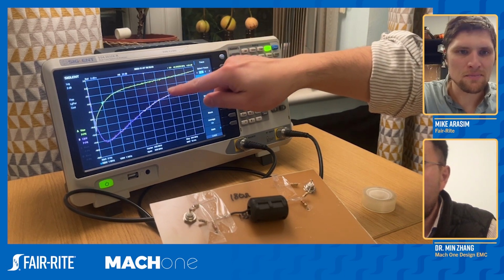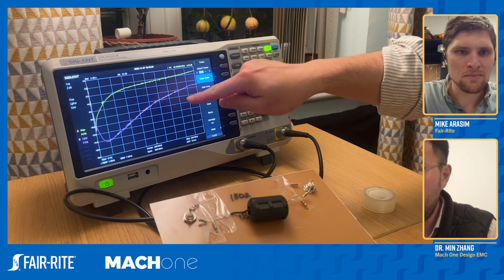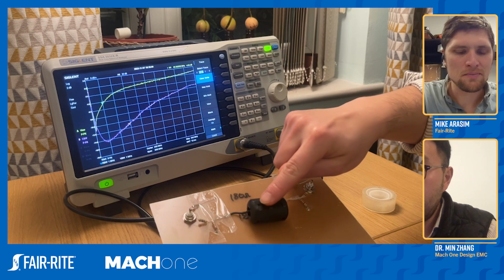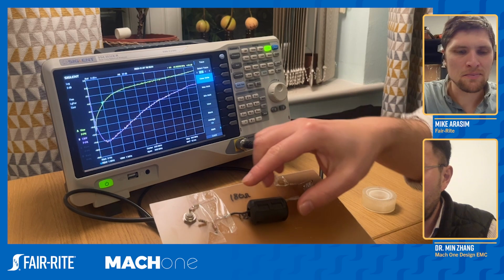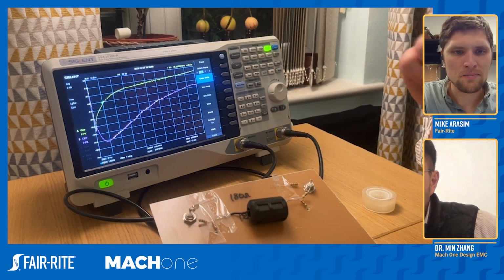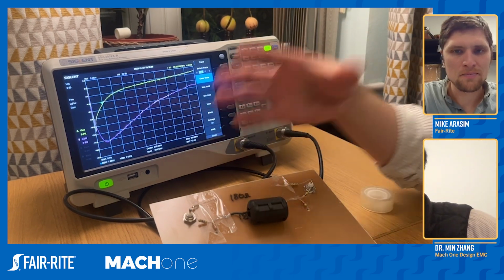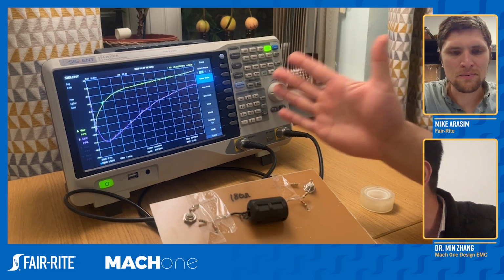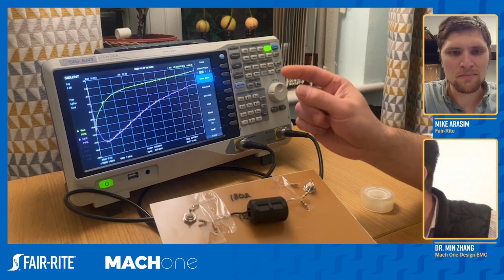Here we already have two traces plotted. It is worth mentioning that before I place the ferrite on this cable, I need to do a normalization first, for the exact reason that you just said. We are measuring frequency, in this case, up to about 500 megahertz.